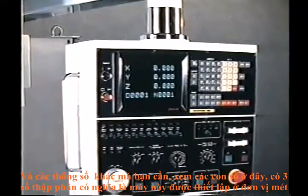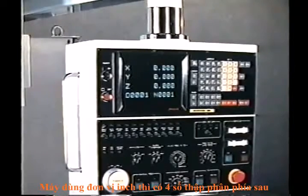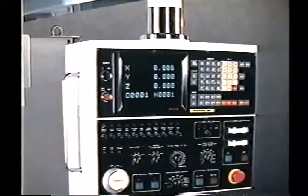And you notice something kind of interesting here. Take a look at the digits here. We have 3 digits behind the decimal point. That means that this particular machine is set up in metric. In inches, we would always be dealing with 4 digits. We're always dealing in tenths. Where in metric, we're always dealing with thousands of millimeters.